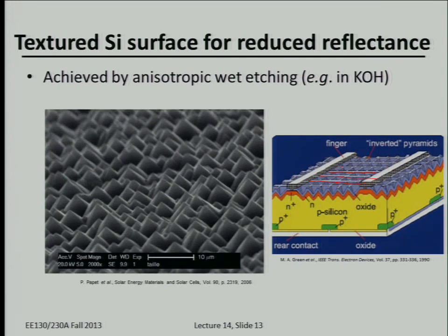You can grow a thin film of silicon dioxide on the surface, and then you can use microfabrication processes to pattern that oxide into, let's say, a grid of stripes like this. Okay, so you have a grid of oxide on the surface of the silicon. But in between those strips of oxide, you have silicon exposed. So I'm just going to draw a cross section. You have some oxide stripes like this on the surface of the silicon.